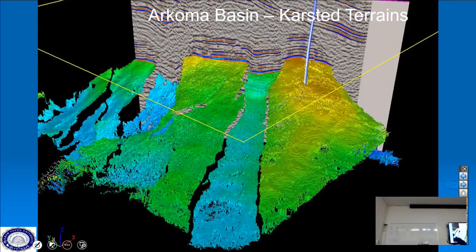What's a karst for my geologist? Is it carbonate? It's a carbonate rock, yep. And what's happened to the carbonate? Yeah. Chemically dissolved? Yeah, so we talk about sinkholes. You get karstic topography. You could actually have a layer here of carbonate, another layer of other sediments atop it. And if the water, the hydrologic features coming through here erodes this away, you can actually have this create a hole and this collapse into it. In the event that all this is away, we can still karst it. So Florida today is largely karsted terrain.